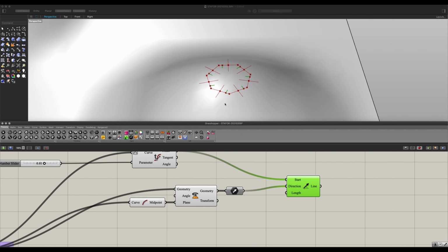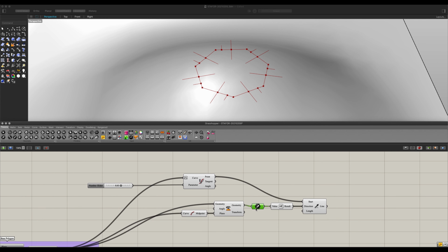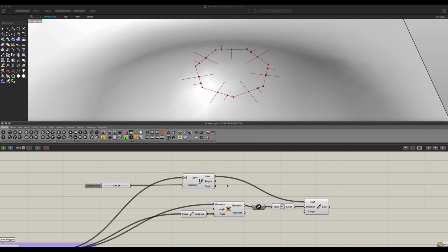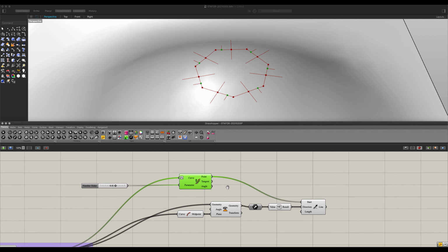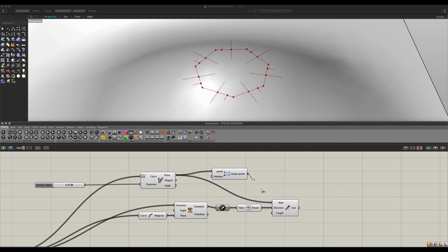And if by any chance these turn in the wrong direction, just add in a negative value. Place it into there, and they will change accordingly. However, there will be times where you won't have shoulders per se, because you want a completely star-shaped fortress. And to make sure that's not a problem, let's add in a remove duplicate points, so that we do not have any extra points clogging our geometry.